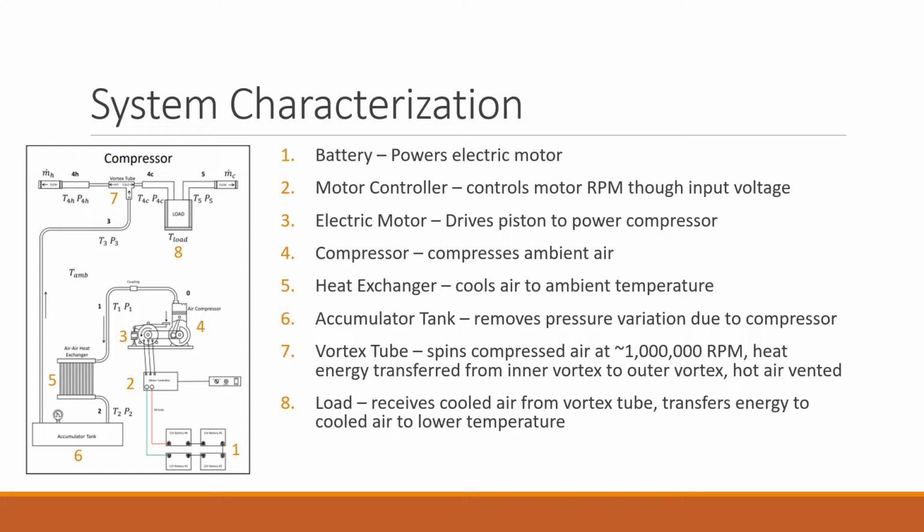There are 6 different locations where temperature is recorded using thermocouples, 4 locations where pressure is recorded with pressure transducers, and 2 locations with flow meters on the hot side of the vortex tube and after the cold air has passed through the aluminum block. All sensors are connected to a myRIO Elvis3 board, which collects data in a custom LabVIEW VI.